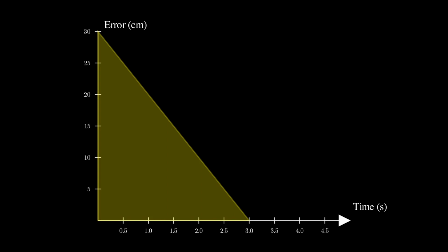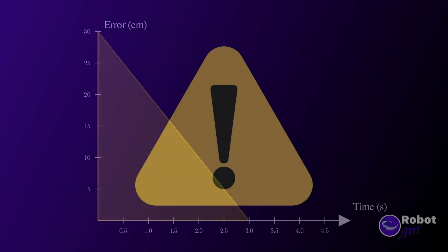This number seems to ramp down nicely, but we can't really use it directly because it goes from 30 down to 0, and our motor speed is probably either a percentage or a voltage. I'm going to pause for a moment and pay special attention to this problem because it's a pretty common beginner mistake.